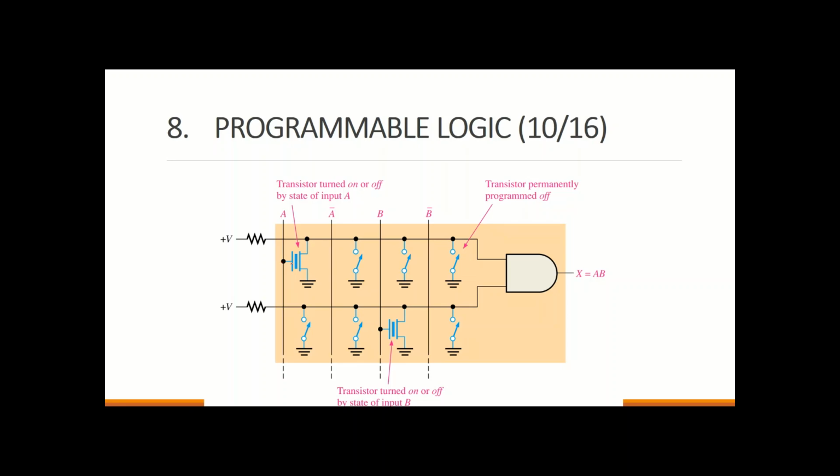If it is 1, the transistor will be on, and this output voltage will be connected to low ground. And what happens? The input here also will be connected to ground. Or in other words, it will just display the A state itself. Otherwise, it's always connected to high. It wouldn't change the other part.